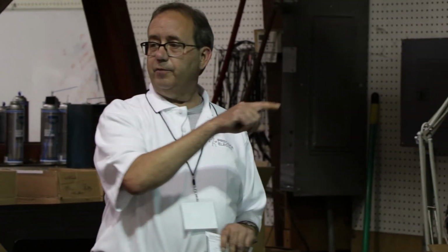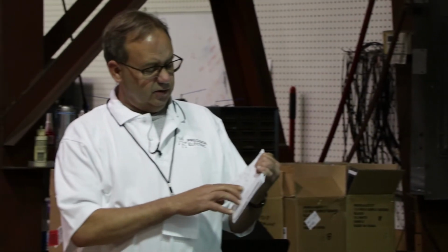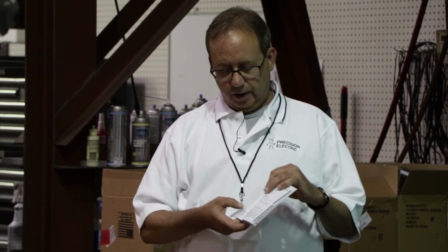If you put it in and it runs backwards and it's a compounded motor, and you want to change the direction of rotation, you have to change A1 and A2. Or you can walk up to the drive maybe and just change it that way. But this can be kind of a pain because it's bigger wire, especially when you get into some bigger motors. You got to break that S1, S2 connection open, and it's all taped up.